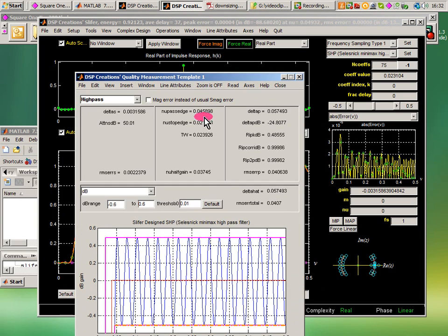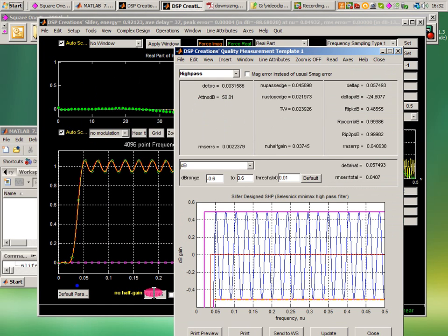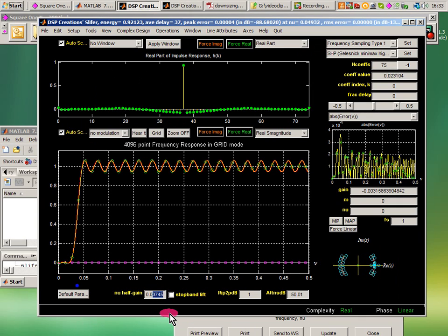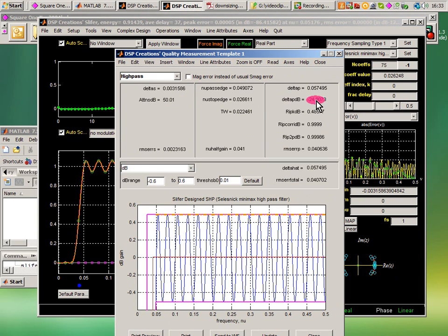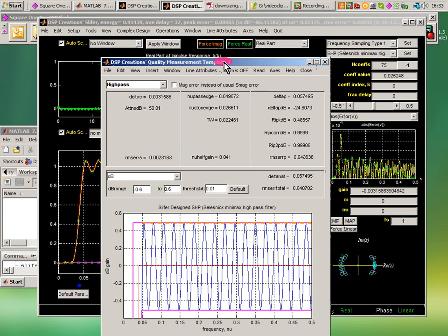So for this relaxed problem, I see that the transition width is okay. This edge is a bit low, not too good. Otherwise, if I can bump this back up somewhere, then I'll be probably in. So I do this by going down here to a nice number of 0.041. Check this. Still, everything is okay on the outliers here. 0.022. Now I'm just above, just below. So now I've met this other solution that we heard about.